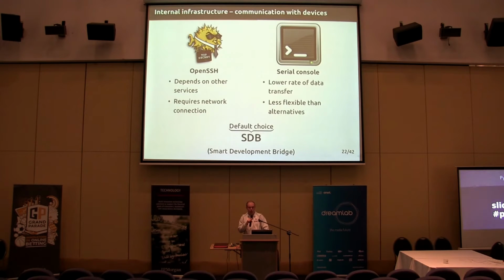without hassle. As for the communication with devices, we considered multiple protocols. The first one that comes to mind is SSH, but it depends on other services like networking. It also depends on the connectivity provided by the board itself. Not all the boards that I showed you earlier are equipped with an Ethernet port. Some of them, like HiKeys, are wireless only, so it was not the way to go. We also considered serial console, which is the basic way of communication in the embedded world. However, it offers a low rate of data transfer, and it's not really flexible